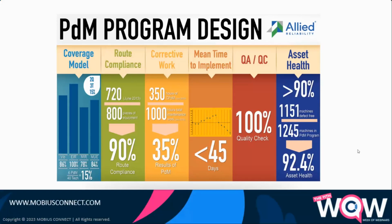That's your target. Mean time to implement, very important. If your condition monitoring program is in place and you're identifying defects, but you're not acting on them in a reasonable time, then you're increasing risk, in some cases significantly, to the organization. So you target less than 45 days for mean time to implement. That's from the point of defect identification through corrective action completion.